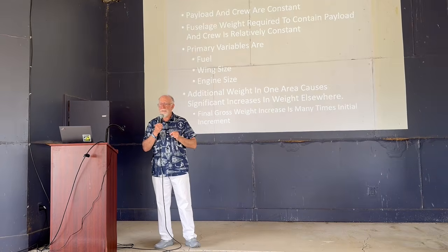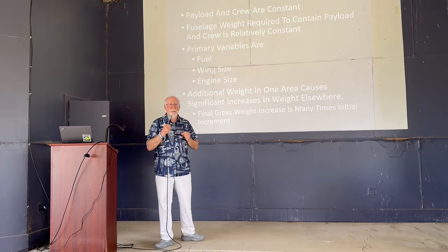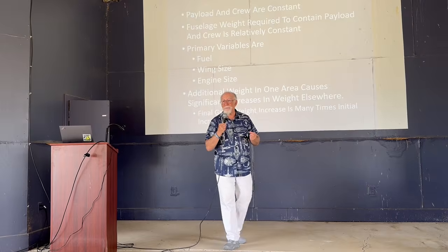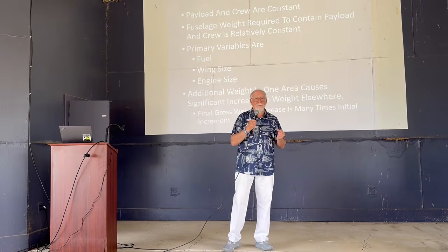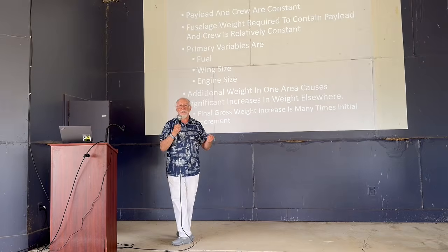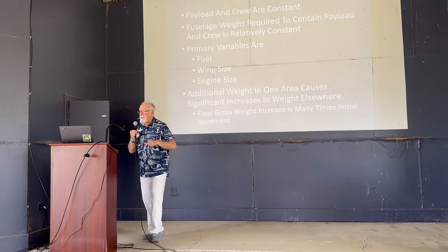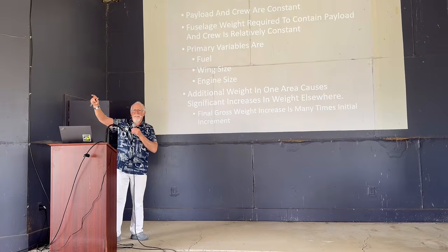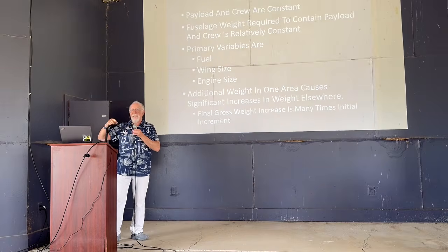Oh, but I have to maintain stall speed, right? That makes the wing a little bigger, which is a little heavier, which means I need even more fuel, which means maybe I need a little more engine. And by the time you get done with that iteration, you've gained between 3 and 5 pounds. So weight is one of those cycles that can be either a virtuous cycle as you take weight out or a really wicked cycle as you add weight.